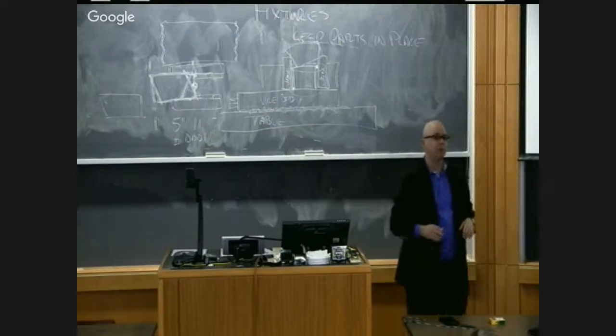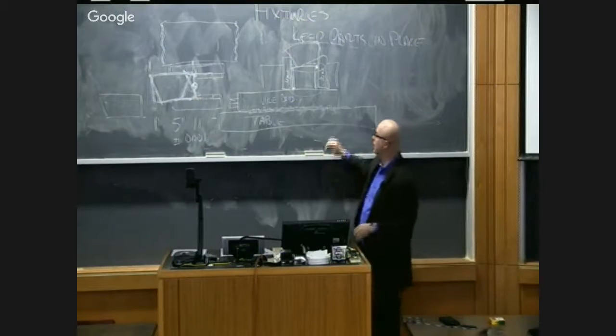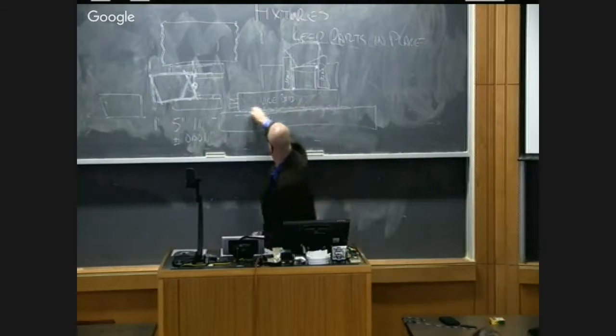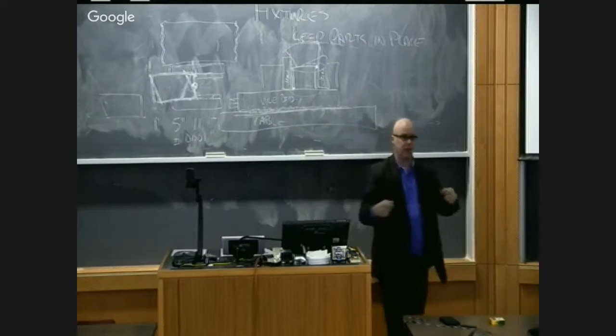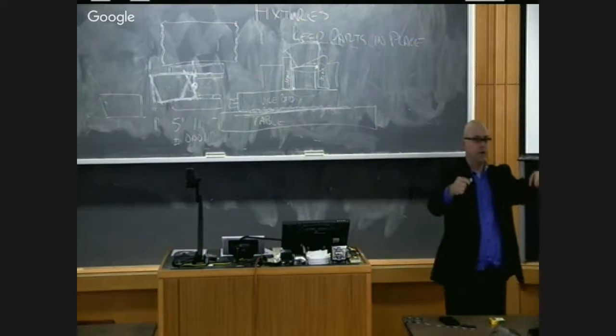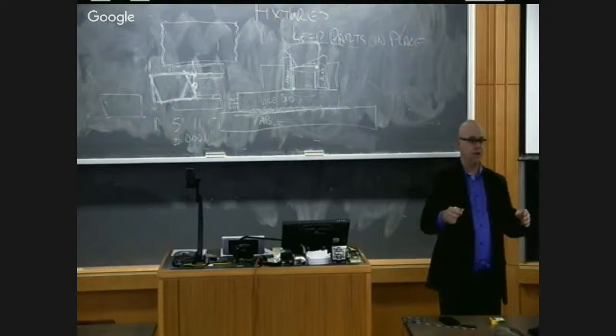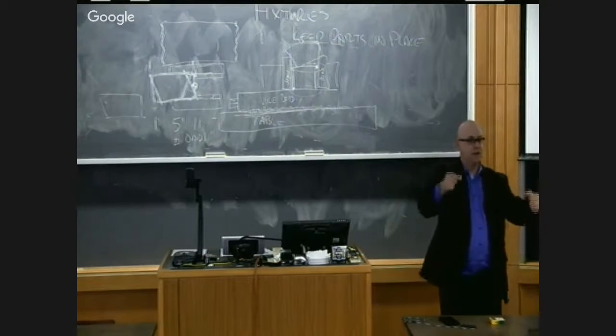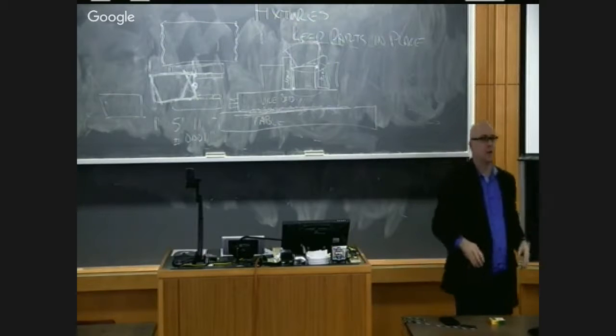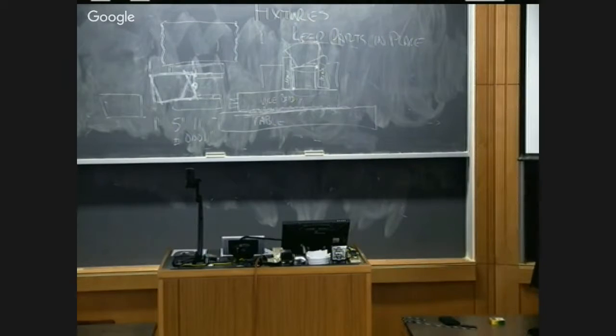Because when we set up the machines before we put the vise on it, we put a precision level on this table, and you can actually adjust the little feet the mills sit on. You can adjust the tension in the casting, the stresses in the casting, by adjusting those feet, and you can actually twist that table. So we level the table. So you could put a level on it for that. What about skewness this way? How do we fix that?